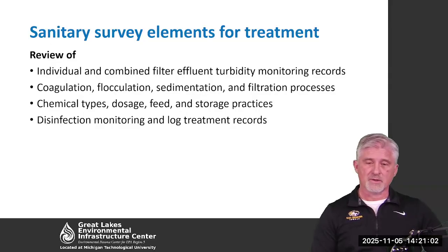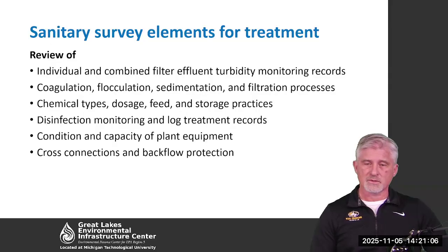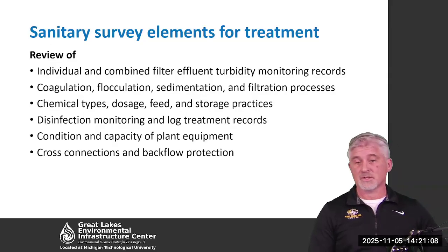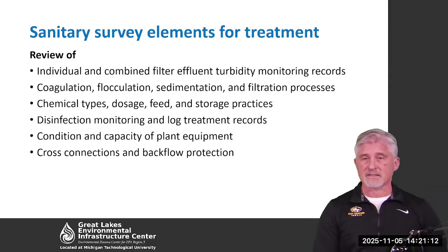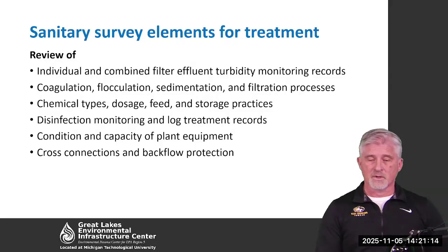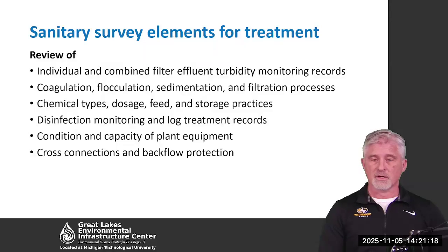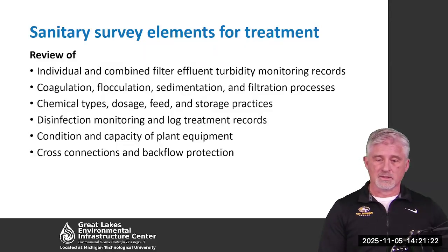Your disinfection monitoring records and your log treatment records, they're going to look at those. What's the condition of the different components of the plant and the capacities of those components? Do you have an active cross-connection control program to rule out backflows?